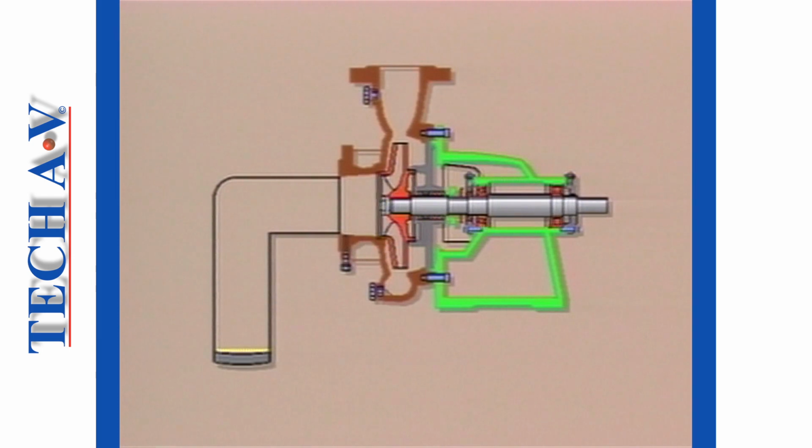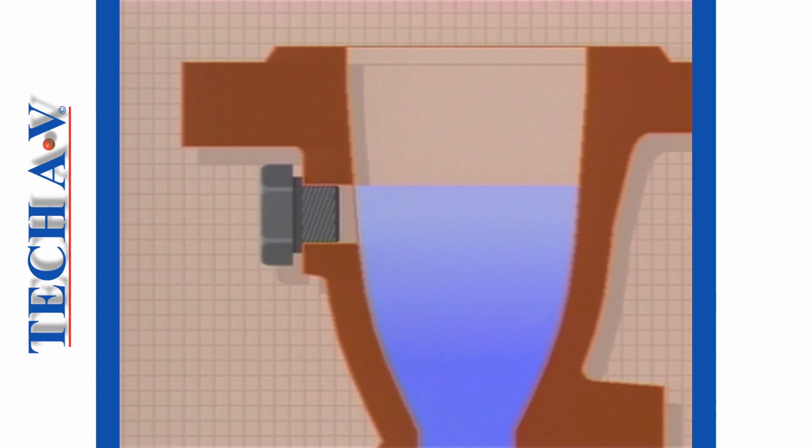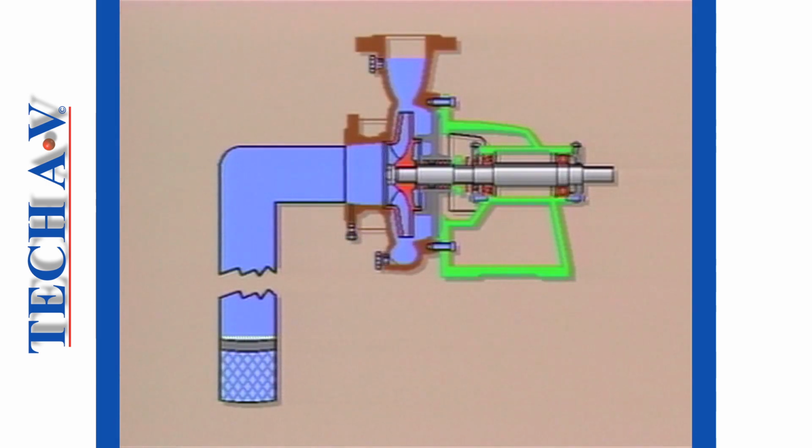A pump working against a suction lift has to be primed before it will operate. Simply stated, priming means that the pump's casing plus the suction pipe must be full of liquid and free of air or gas. Most pumps have a priming plug situated above impeller level. The pump is filled to the level of the plug, and the suction side of the system is thus primed.